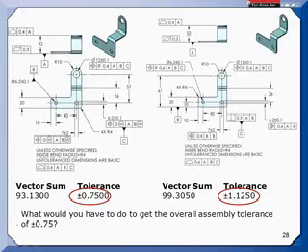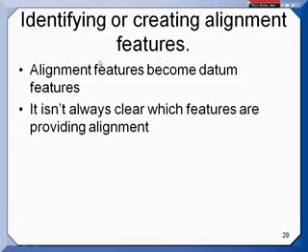So on something like this, I would never bother putting a perpendicularity or a position or any kind of feature control frame on that feature, because I'm not worried about that feature. As long as they hit the size, I'm happy, because I know that the datum itself is going to be correct.